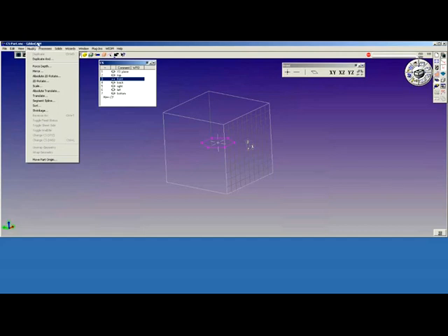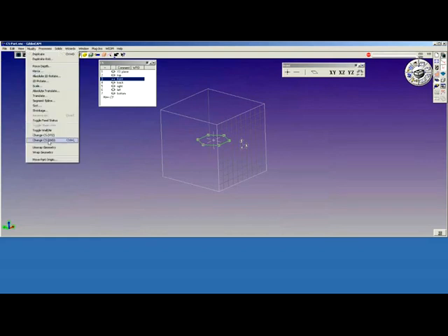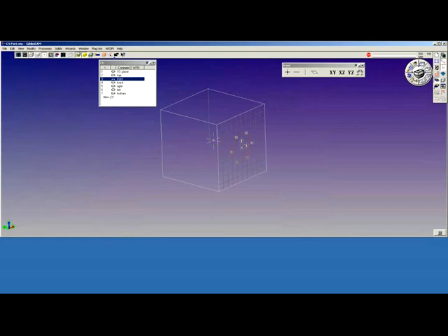And to illustrate this, I'm going to double click the geometry, and you notice that I've changed CS to the front. My intention is to take this geometry and move it to the coordinate system that's active. Select the geometry, modify, change CS HVD. As you can see, the geometry snaps to that coordinate system and changes color to blue. The relationship of the geometry to the origin of the coordinate system is maintained.